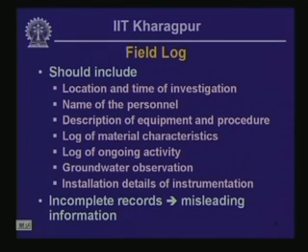It is extremely important to have a very complete record of whatever is going on during the subsurface investigation, because the investigator's report is the only thing that gives the designer of a particular facility the details of what happened during the subsurface investigation, and if the records are incomplete, then the inference that the designer draws from the field record is going to be insufficient and often misleading.